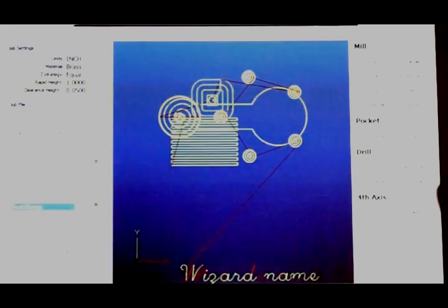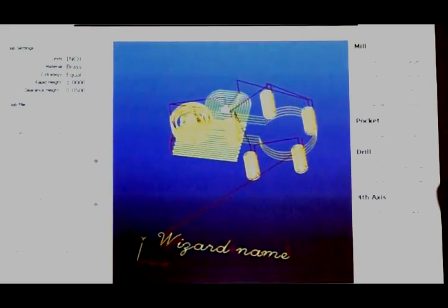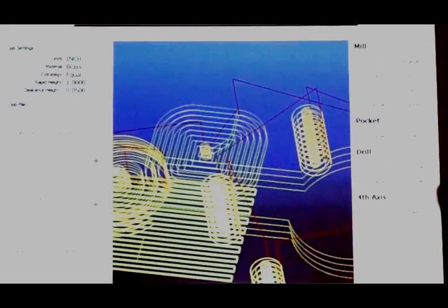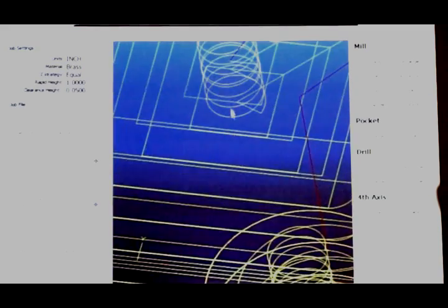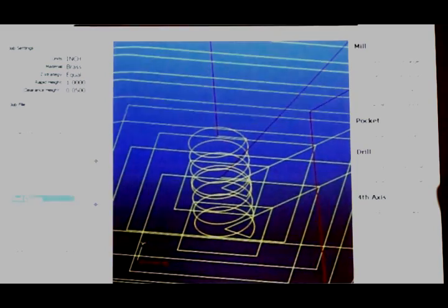And notice you could put that tool change and just push it up. Say we wanted to do the pocket and the hole with it. You can add one at the bottom and force that same tool up through, push it up in the list, and use that same tool for the ramping and stuff. He probably already showed you the ramping. We can edit it and tweak that stuff, or just take out the ramp, set it to 0.